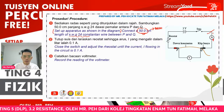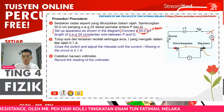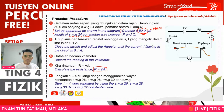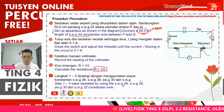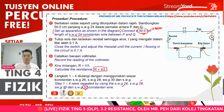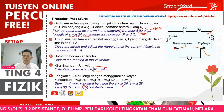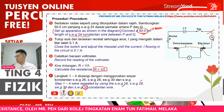Then you have to read your voltmeter reading so that we can get our R by using this formula I also mentioned already just now. Then repeat steps 1 to 4 with different thickness of wire, shown by different SWG readings. The greater the SWG reading, the smaller the cross-sectional area. We also advised on this already just now.